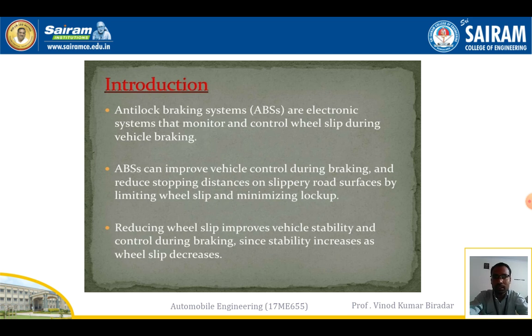By using this, it can improve the vehicle control during braking, and it will reduce the stopping distance, normally on slippery road surfaces and on inclined roads. It will not only control the slip, it will reduce the wheel slip, improve the vehicle stability and control during braking, and it will also let the driver keep a stable hold on the steering.